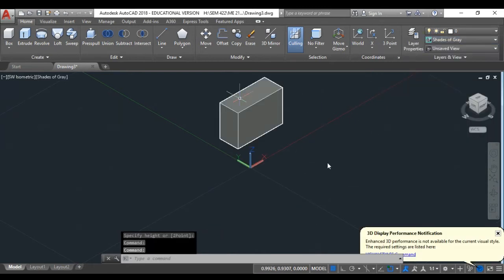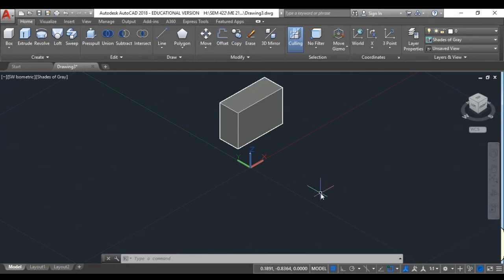Now, guys, if I told you that this is the 3D object, and I'm asking you to tell me if I am looking for the front view of that object, this means that I have to look at which plane: XZ plane, or ZY plane, or XY plane? Assuming that that box is the object itself, which plane do I have to project that view in? Is it XZ plane, or ZY plane, or XY plane? ZX, exactly. And this is exactly what we used to do.